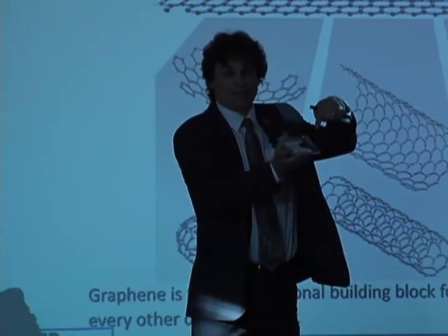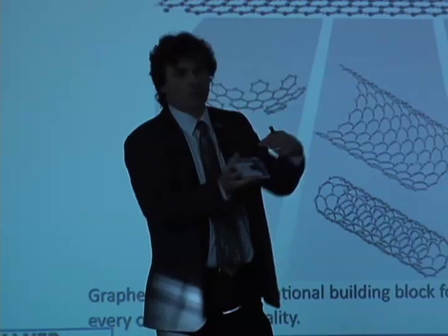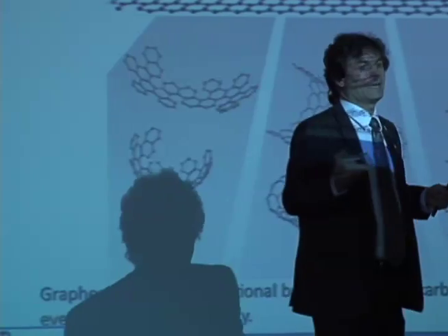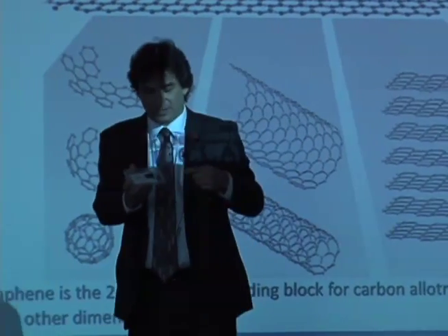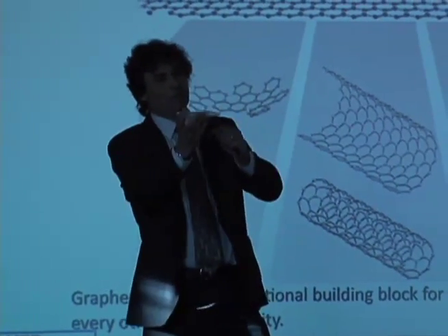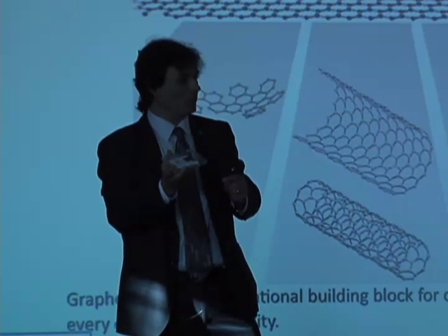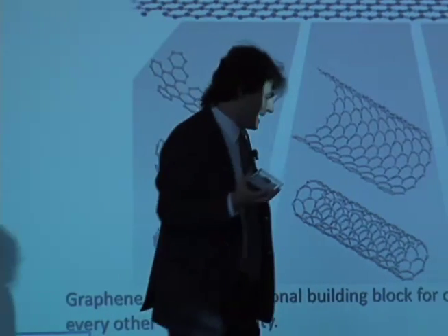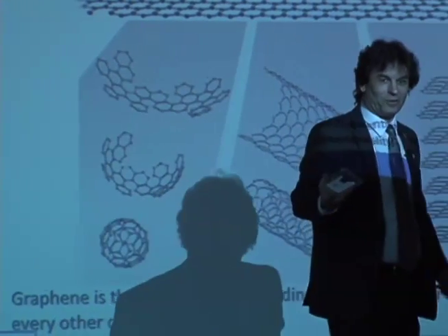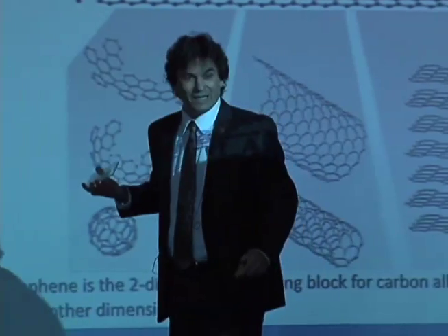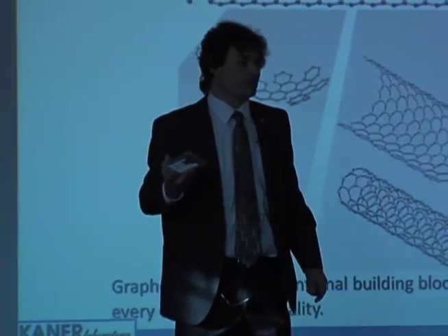On the right-hand side, you will see silicon with an oxide coating. We've grown by chemical vapor deposition a single layer of graphene and transferred it to it. I'll explain how to do that in a moment. If you look at this when it comes around, you'll see this interference pattern, and you shouldn't have any problem seeing it. Now, that's actually not seeing graphene, right? That's an interference pattern. But it turns out graphene is the darkest material ever discovered. A single layer cuts down 2.5% of visible light.